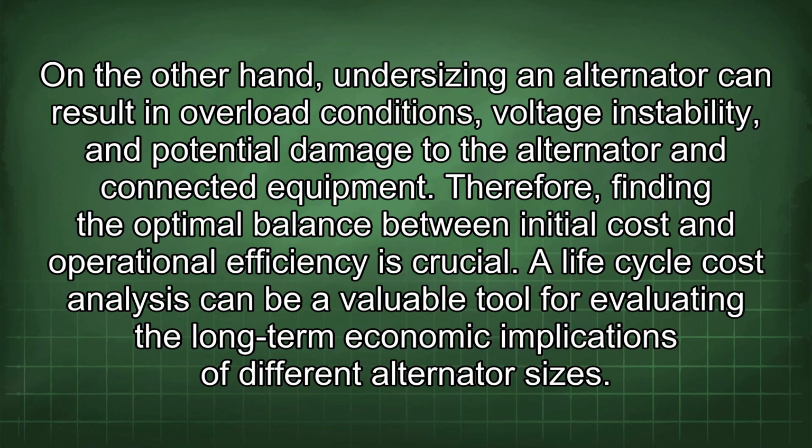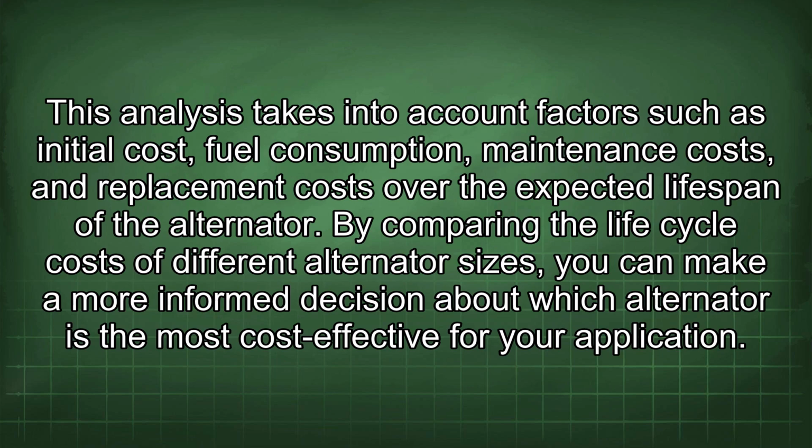A life cycle cost analysis can be a valuable tool for evaluating the long-term economic implications of different alternator sizes. This analysis takes into account factors such as initial cost, fuel consumption, maintenance costs, and replacement costs over the expected lifespan of the alternator. By comparing the life cycle costs of different alternator sizes, you can make a more informed decision about which alternator is the most cost-effective for your application.